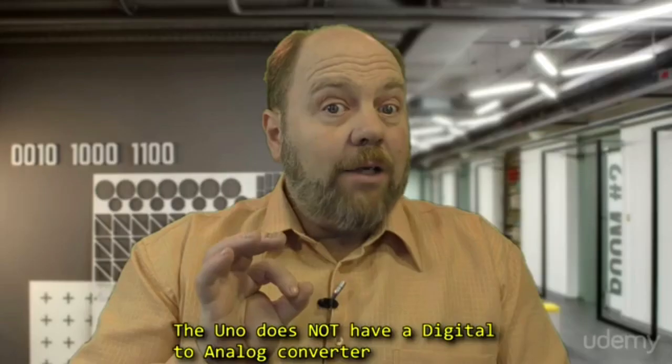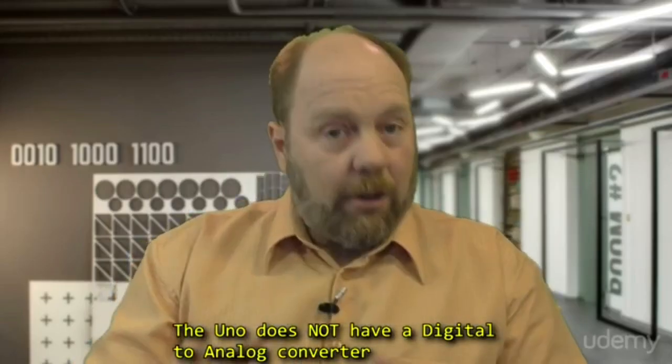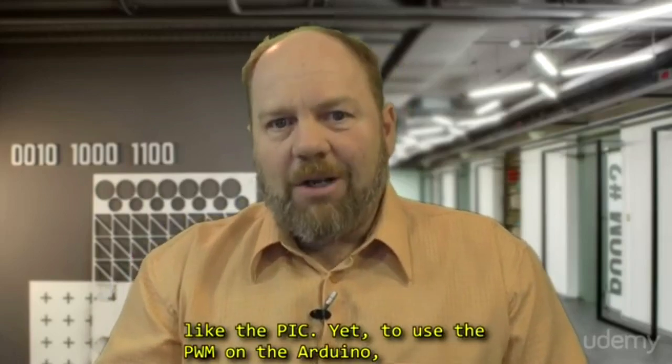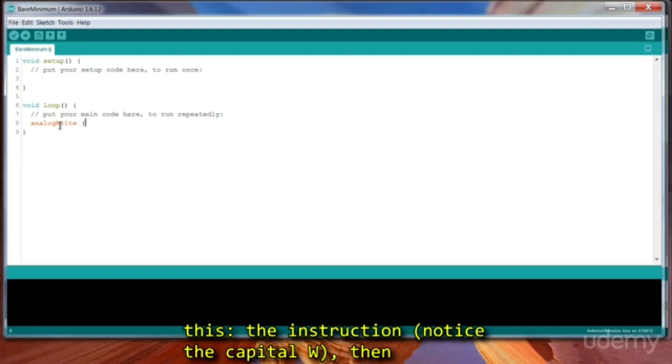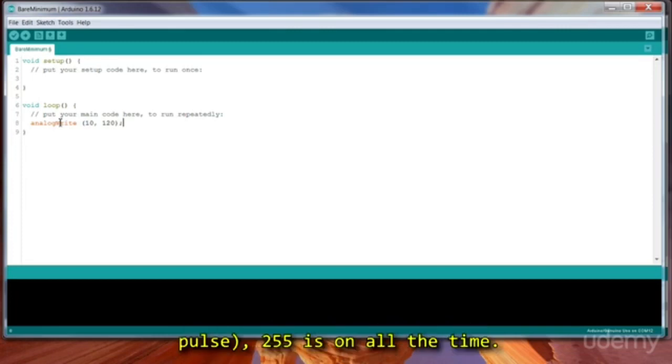The Uno does not have a digital to analog converter like the PIC. Yet, to use the PWM on the Arduino, you use the analogWrite function. That looks like this. The instruction, notice the capital W, then in brackets the pin number, a comma, and then a PWM value between 0 and 255. 0 is off completely, no pulse, and 255 is on all the time.